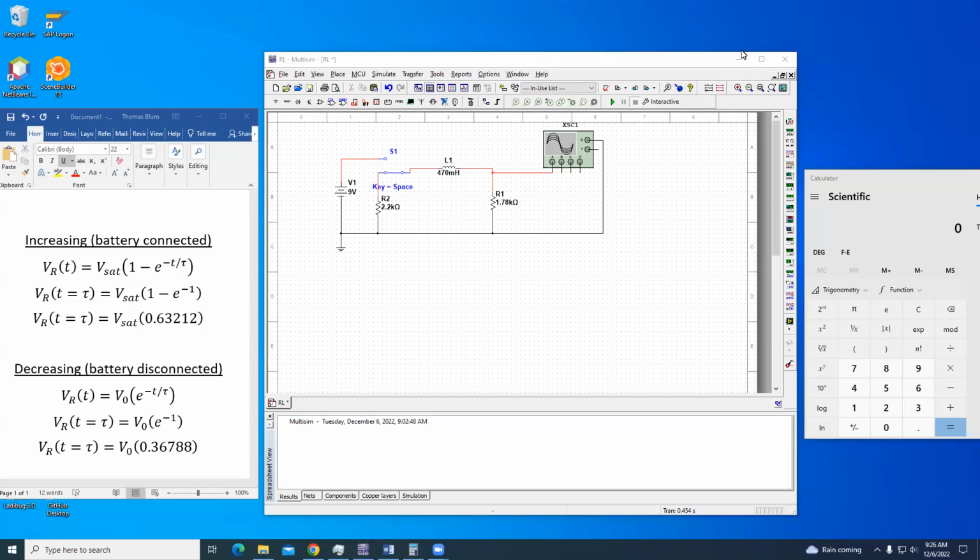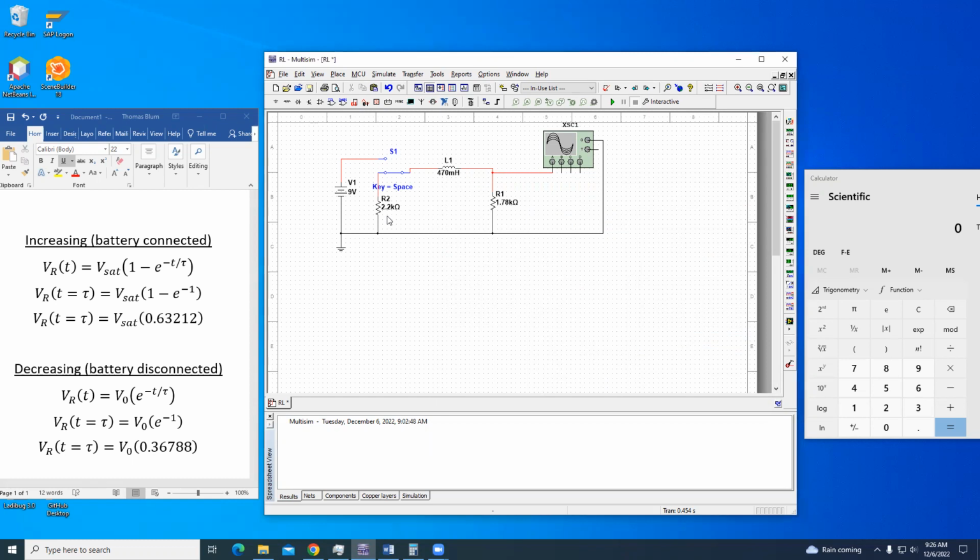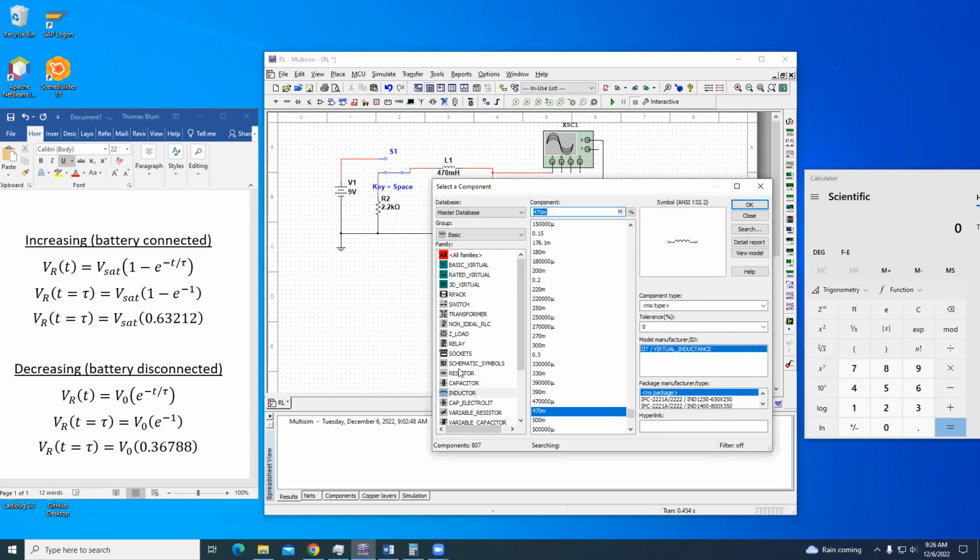I'm looking at a circuit with resistors and an inductor, a DC power supply, which I'm just going to call a battery, and an oscilloscope. Those items in National Instruments Multisim are found under the ground and power sources. The inductor and resistors are found under basic, inductor, resistor.